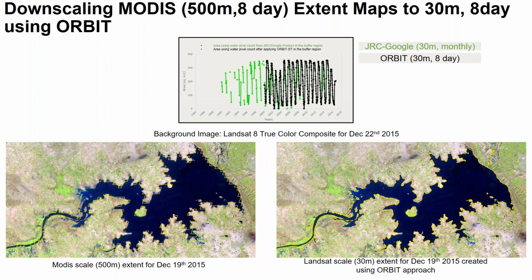We have done similar downscaling using 10-meter USGS elevation data that's available for the US. So basically, if the elevation data is available, or if we have labels available over a period of time from which we can infer an implicit ordering, we can perform this kind of downscaling. And because we can construct this downscaling on a daily scale using the MODIS data that's available on a daily scale, we can actually use this information to create hydrographs, or even, using some other techniques, construct the changes in the water volume in water bodies, which again could be used to calibrate hydrological models.